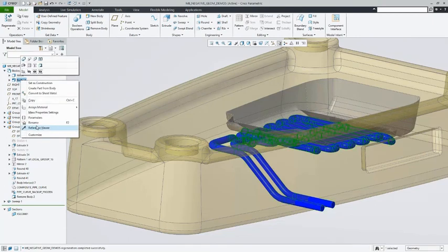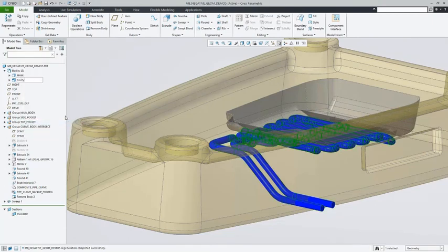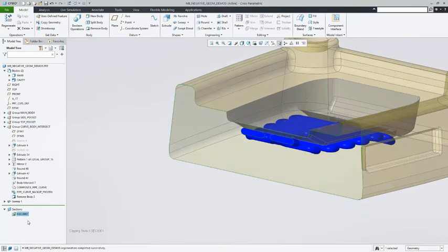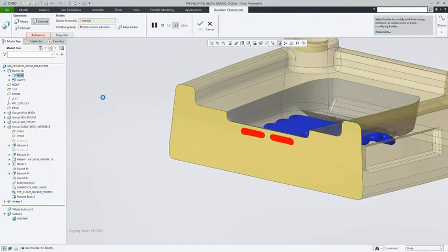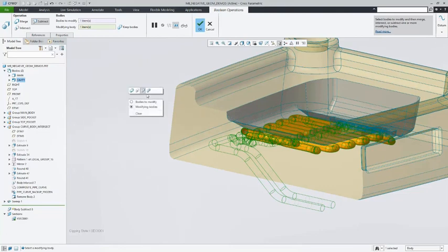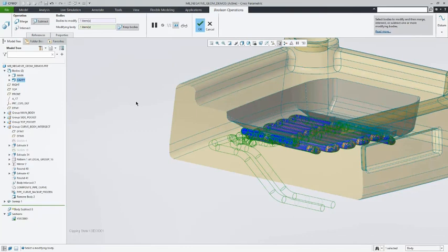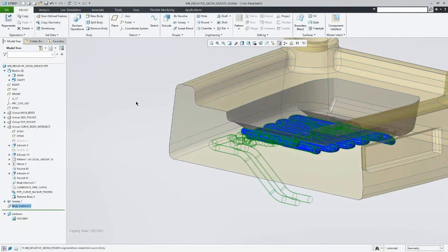As you can see, the representation of the cavity as a solid body during the design process already provides more flexibility in visualizations. Not only can you apply appearances to bodies and independently show or hide them, also cross-sections support the body concept with a broad range of new capabilities. You can, for example, easily visualize body interference areas within the cross-section in a separate interference color. The red interference area will of course disappear when you remove the interference by subtracting the body geometry from each other.